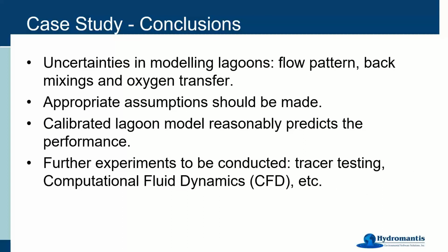So just to conclude, modeling lagoons usually involves a lot of uncertainties, such as determining the flow pattern within the lagoon, adding back mixings and recycles, and also determining the oxygen transfer rate. So when there is a lack of information, we need to make appropriate assumptions.